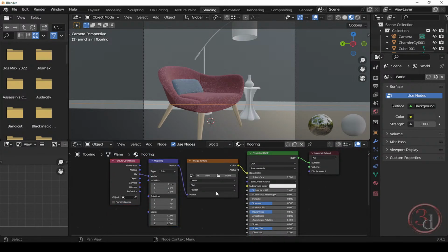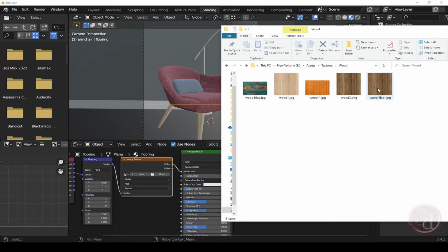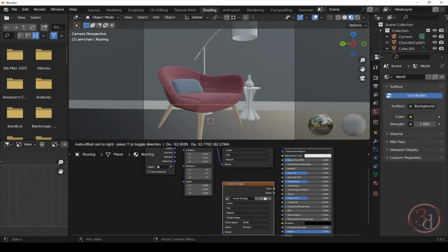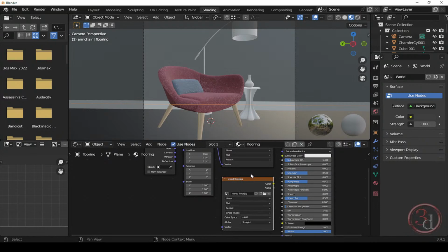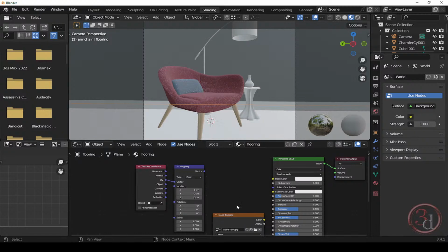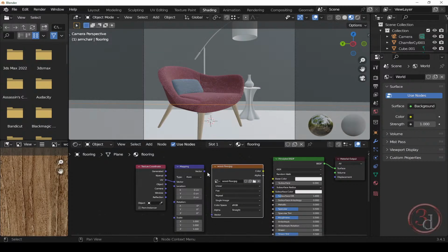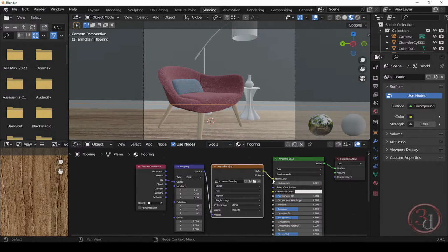Very good. So this is the texture. So what I will do is go to my Explore window and click and drag the texture node. Very good. All I have to do now is get rid of this one, and I will reconnect this texture node with the vector going to vector, and then color goes to base color.